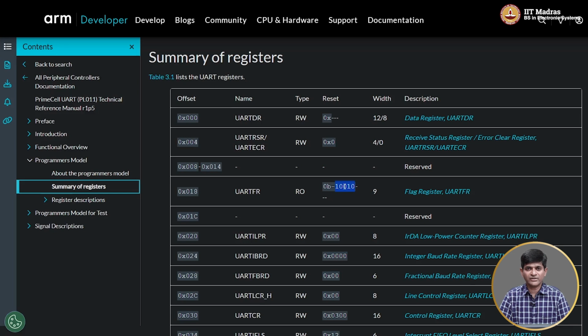So, as we know, when you bring up a system out of reset, whenever you are writing Verilog, you should have an always at posedge clock or negedge clock, as you might choose. Immediately after that, you should have a condition which checks for what to do with reset. Depending on whether it is a reset active high or active low, you need to decide for each and every bit that is present in the system, should the bit come up as 0 or as 1. The common case is that we assume that it is going to come up as 0, but what this indicates is it is entirely okay to also have some of the bits come up as 1 after reset.